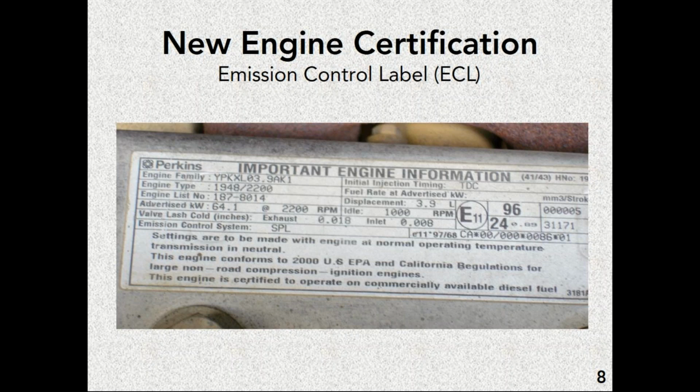PKX, the next 3 digits, are always going to designate the manufacturer of that engine. So Perkins Engines, if they manufacture an engine, all their family names are going to say PKX in the next 3 digits. The 5th character is something of interest if you want to know what service class this engine is made for. L is actually the single most common letter that you'll have associated with off-highway, off-road, non-road.